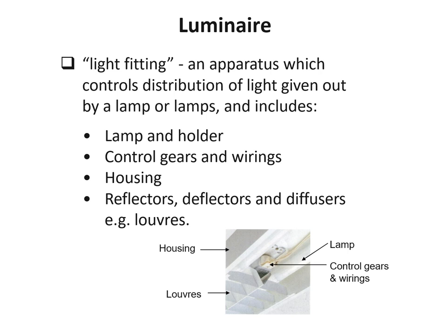And control gears and wirings, this is something that beginners usually leave out, or rather they miss, and it becomes an afterthought, right? So if you are looking in detail design, you need to know what you are designing for. For example, a strip of LED light, if you use it to light up a piece of carpentry, is very nice. But the question that you didn't think about is, oh, then where do we house the transformer, right? And where do we house the switch? Yeah, so those are actually part of the luminaire that we have to think about.